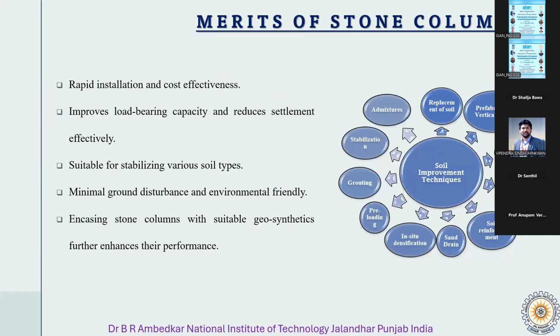What are the merits or advantages of stone columns? First thing is they offer rapid installation. They are very cost effective. That's why they are a popular choice in many construction projects. Secondly, they improve the load bearing capacity of weak soils and effectively reduce settlement, which is crucial for structural safety. Again, they are versatile.